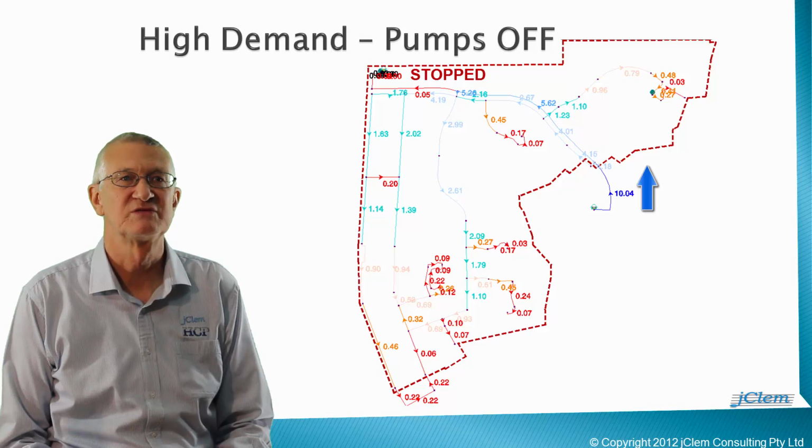Near extremities of the reticulation network, the flow rates and direction will simply continue as they were, heading in the direction of the customers. For several pipes in the system, the continued flow toward customers will mean that their velocity change is only marginal, lowering the rate of velocity change in those pipes, dampening surge amplitudes in their locations. Again, this scenario may or may not be the worst case.